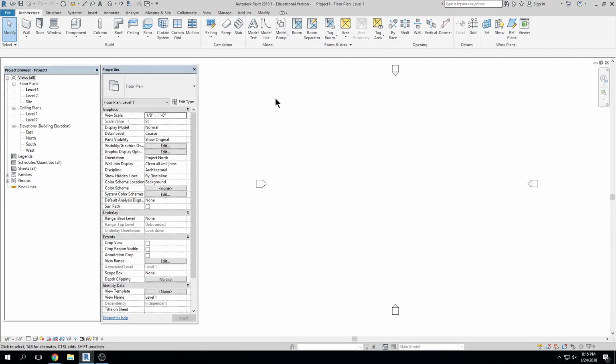All right, so we talked last time about how we can generate some very basic walls and different things like that, navigate the drawing board of Revit. We know how to use reference planes. We know that we have to use dimensions to help us create geometry, right? And hopefully I've conveyed that when you're drawing in Revit, you don't always get the object that you're drawing the right size the first time. So when I draw something, I will a lot of times just get the general shape of something, and then I will use dimensions or whatever to help me get it the exact size that it needs to be, right? Which is somewhat different than AutoCAD, right?